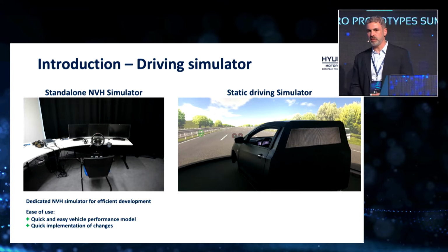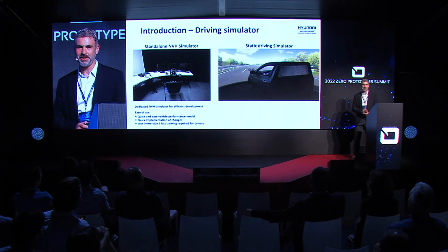It's easy to make changes, so the person can be actually driving the simulator and having the laptop at the side of him and quickly do adjustments and directly drive again. Whereas if you're in a full cockpit, it's quite difficult to have a laptop next to you. And maybe less immersion is not such a positive point, but the benefit of less immersion is there's less time required for drivers to get used to the simulator. And I think some of you know the issues of putting somebody new into a simulator when too much immersion is there, that they very quickly get sick.